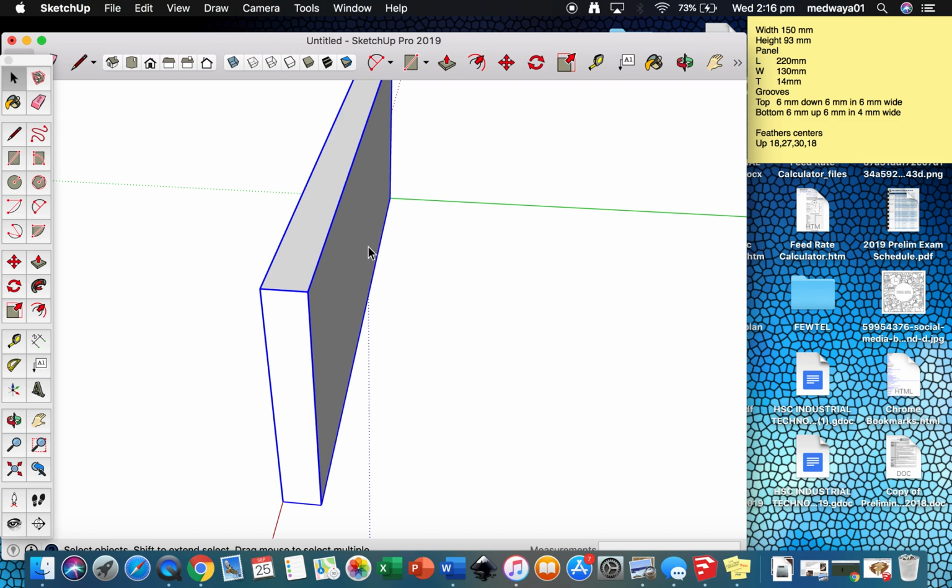So by selecting it once, I can move it around by using the move command. I can resize it, but I can't put holes in it, I can't cut things off it, I can't add things to it unless it's in edit mode. So we're going to edit this. We're going to open it in edit mode, double click, and you'll notice it's got this dotted line around the outside which says I'm in edit mode.